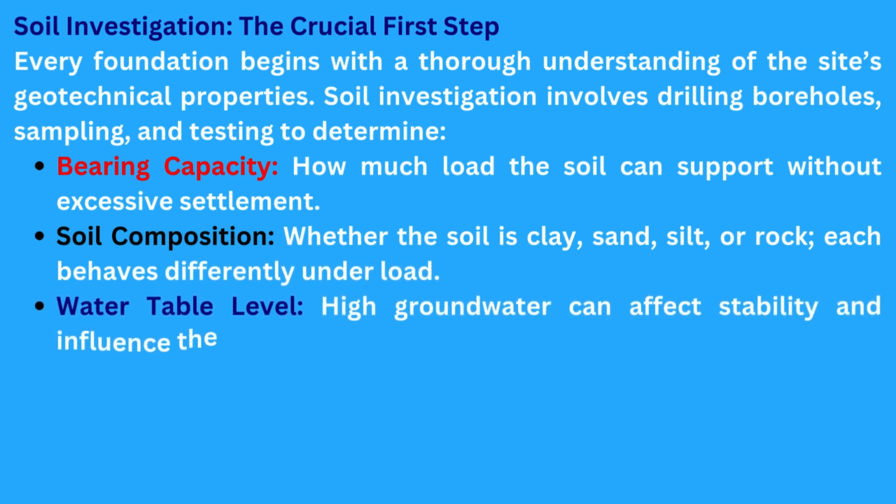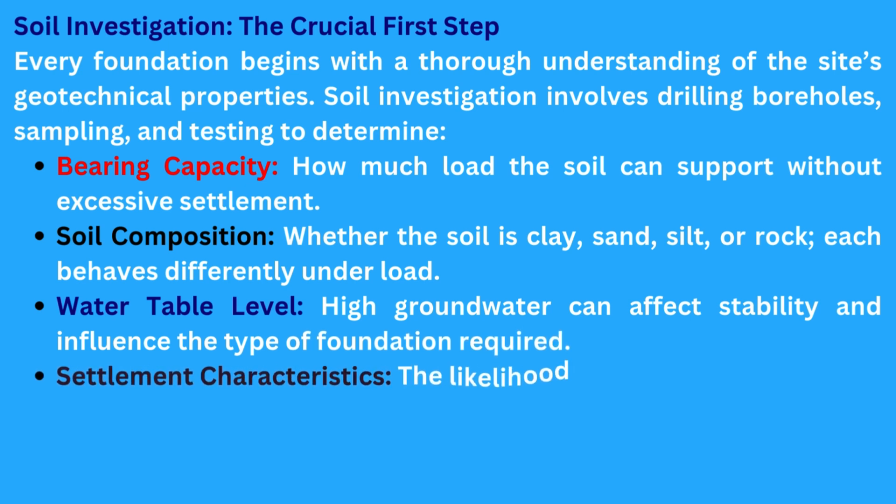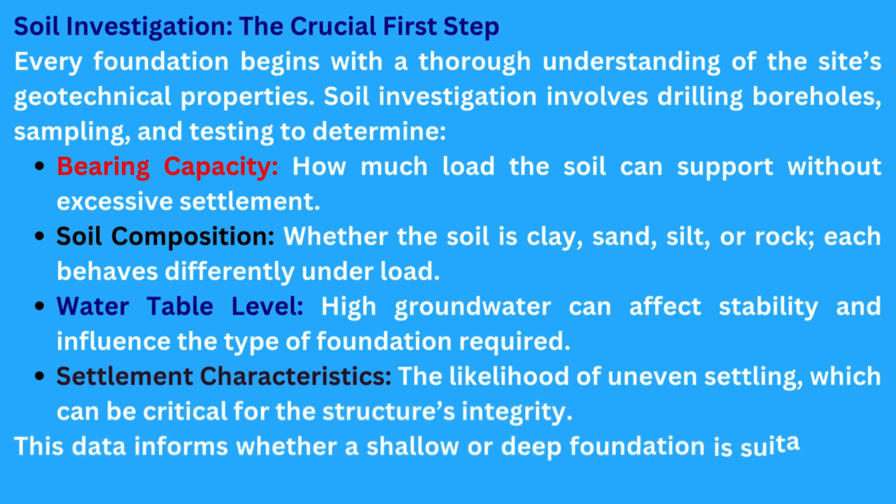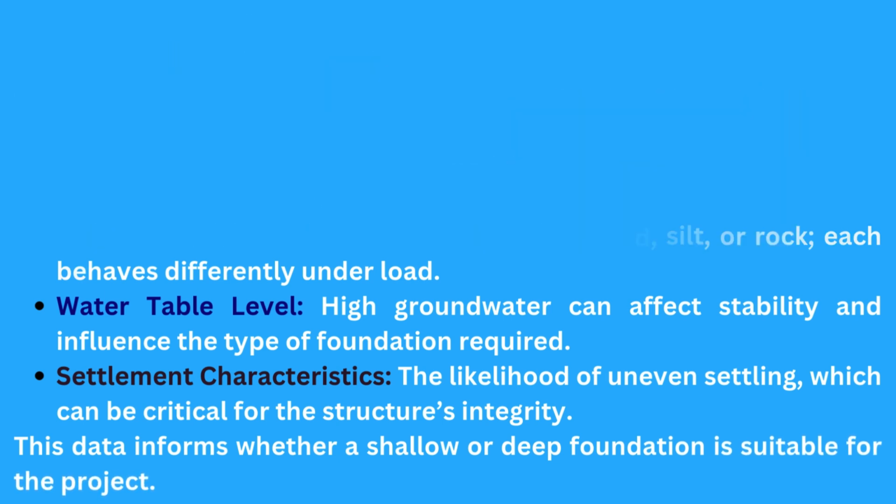Water table level, high groundwater can affect stability and influence the type of foundation required. Settlement characteristics, the likelihood of uneven settling, which can be critical for the structure's integrity. This data informs whether a shallow or deep foundation is suitable for the project.